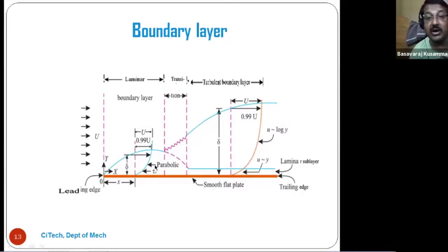Again, one important point: the boundary layer thickness is delta. Below this, laminar flow occurs, more and more laminar flow completely at the surface of the plate. That is called laminar flow. Above the boundary layer thickness, turbulence will occur, understand?